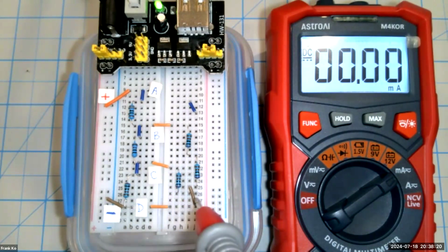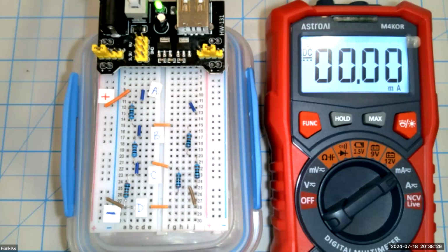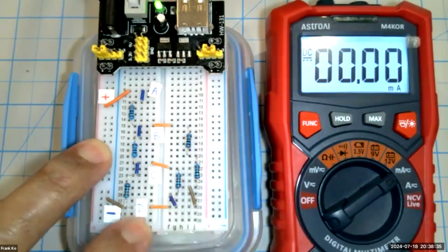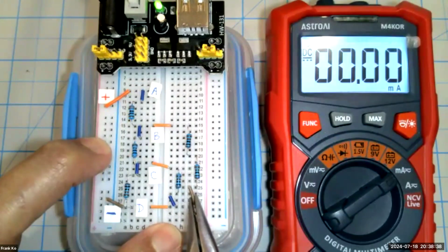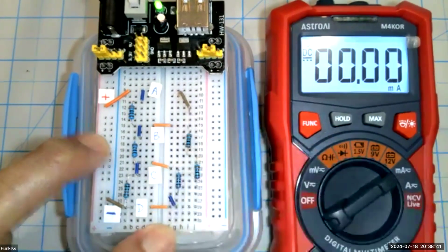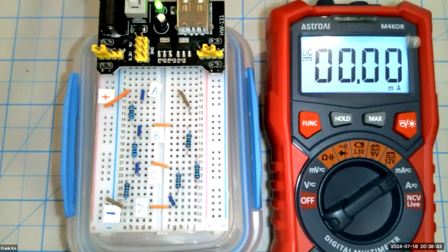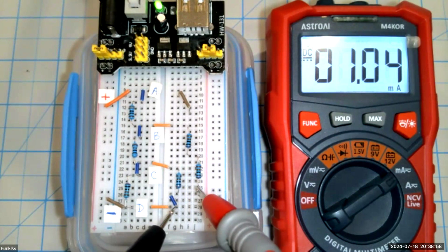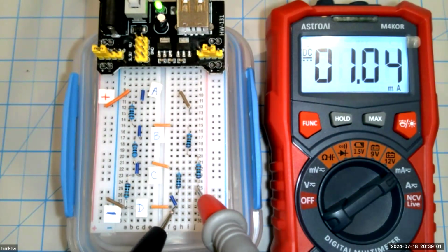Now, if I'm going to measure the next current through the R5 branch, R5 load, I have to yank this jumper. But before I yank this jumper, I have to rebuild the jumper here for the R4 resistor. Now yank the R5 resistor jumper, park it for a moment, and we now have an open. The open is from here to ground. So here's one end of the open, here's the other end of the open. Put the red probe, the more positive side of the open, put the black probe in the negative side of the open. We hope to see something close to 1 milliamp. And look at that, 1.04 milliamps.